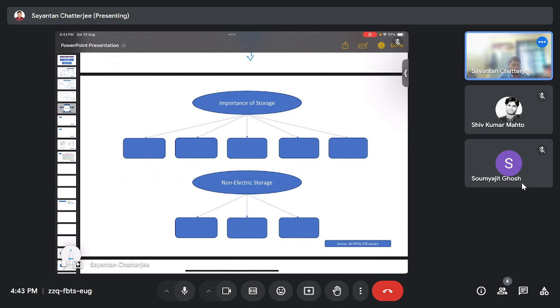So our aim is to make the power consumption profile flat. Since we are in the Indian context, we face two peaks, a morning peak and an evening peak, and we are aiming to minimize those peaks. For that, we need to take the help of the battery energy storage system, because it has the feature of delivering or storing. Another thing is that we all know solar and wind all work in MPPT, maximum power point tracking condition.